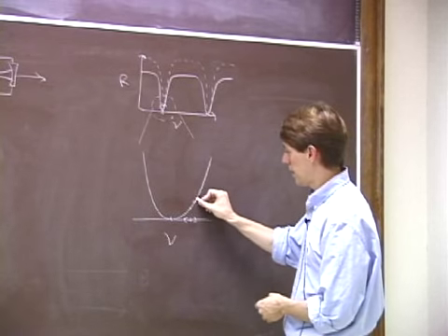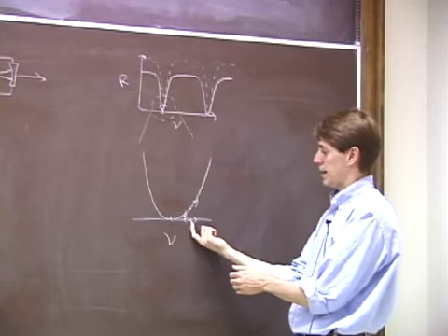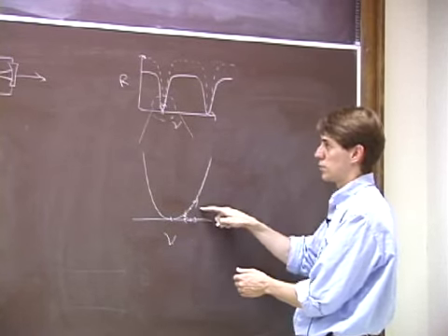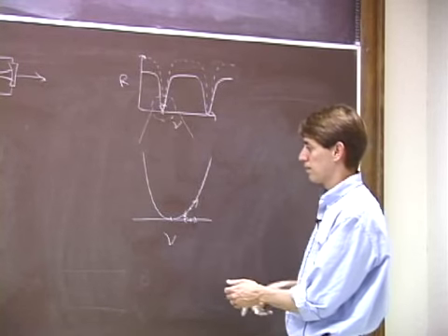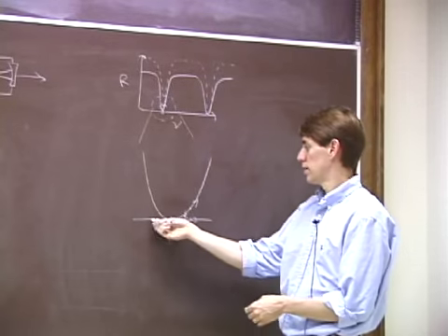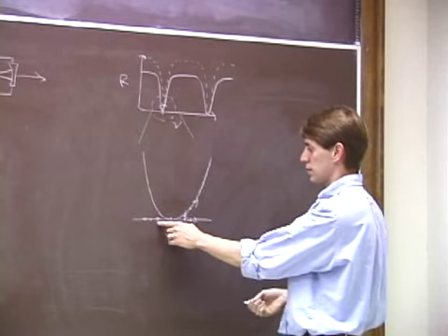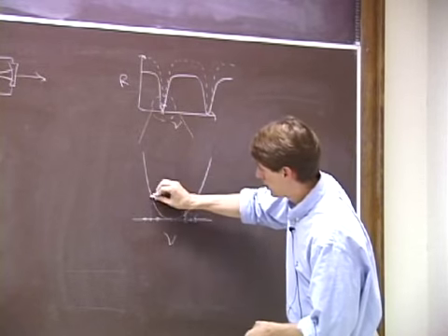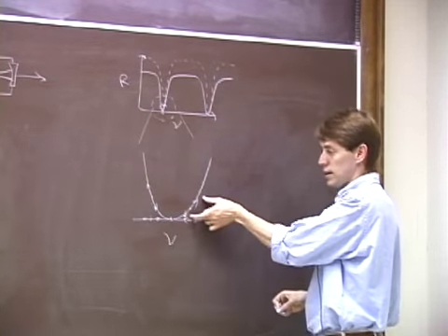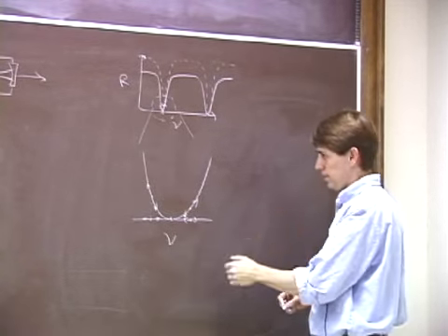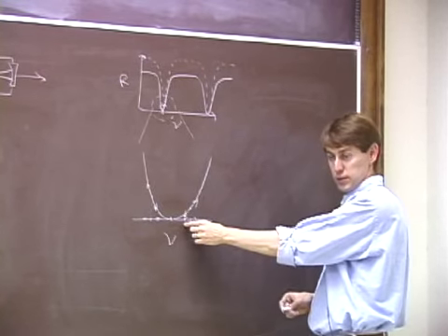then what comes out of the system, what goes into the photodiode, does this. As the frequency gets increased, the reflected power increases. As the frequency decreases, the reflected power decreases. On the other side, it's the other way around. Over here, if I increase the frequency here, then the reflected power goes down. So there's a sign change between here and here in the change in reflected power versus the change in the laser frequency.